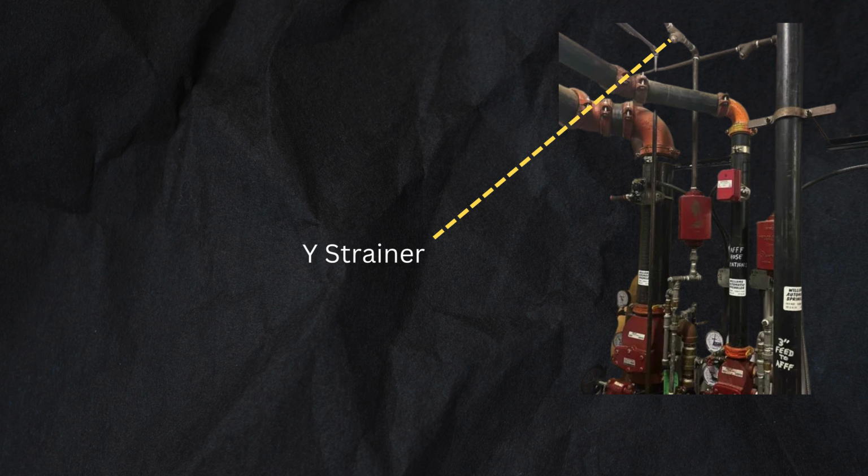The surge of water that occurs when the valve trips can seriously damage the device. Paddle-type water flow devices are also permitted to be installed on wet systems that supply auxiliary dry pipe and/or pre-action systems. Where a retarding chamber is used in connection with an alarm valve, the strainer shall be located at the outlet of the retarding chamber, unless the retarding chamber is provided with an approved internal strainer in its outlet.